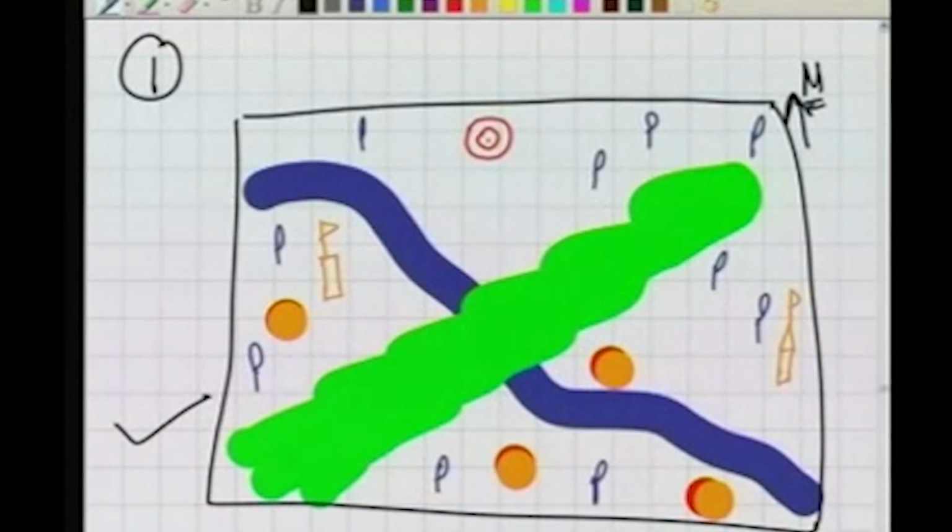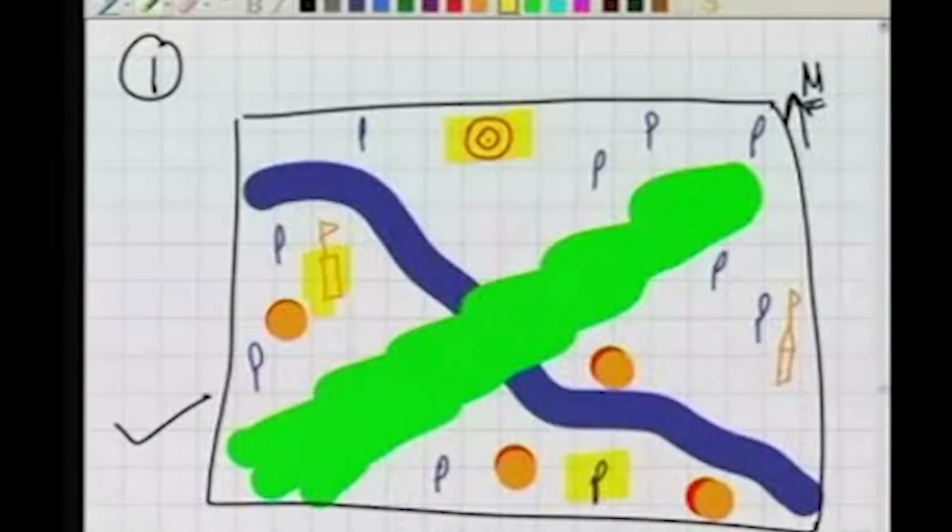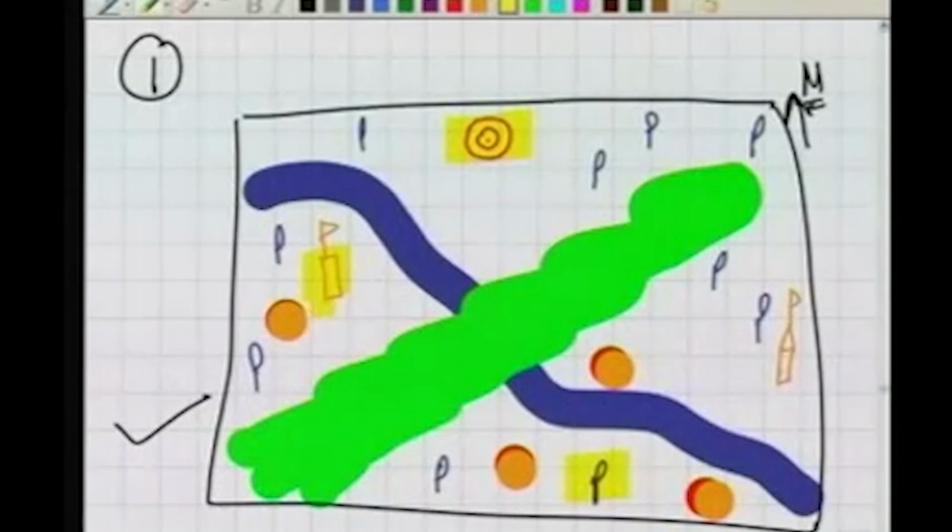Wherever I am, I do not know, but I want to locate it. The procedure is, standing here, I first locate some permanent points in the field which are also plotted. For example, let us say I locate a temple or maybe a tower and a tree. These are three permanent things which I can see in the field. I can identify, yes, that tree is there, this tower is there, or this brick kiln is there, or this huge electrical transmission tower is there. Some of the things which can be located.